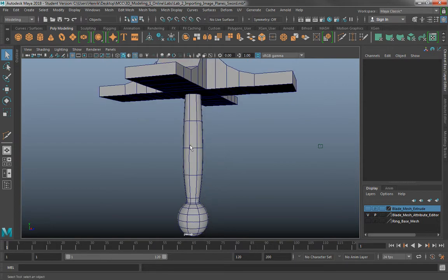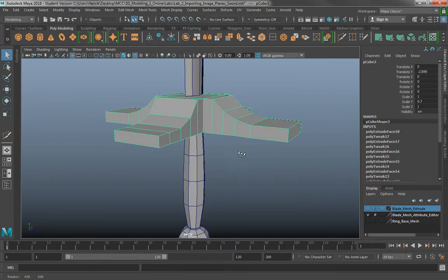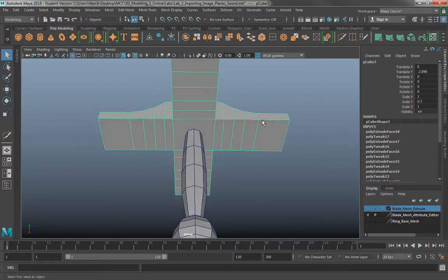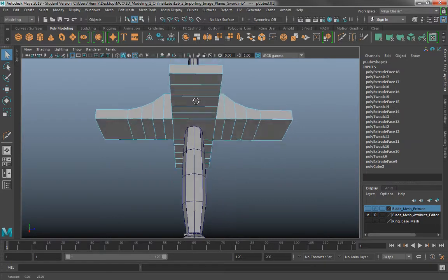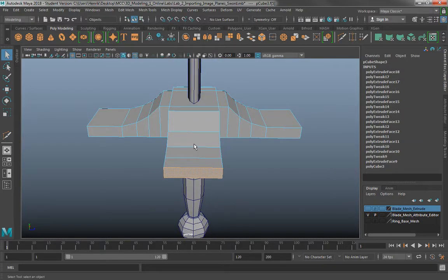Now, getting back to this, in my object here, I want to make sure that there's another way to subdivide faces. And I showed you the multi-cut tool, and how to custom cut using it, and also how to hold Control and equally subdivide it that way.